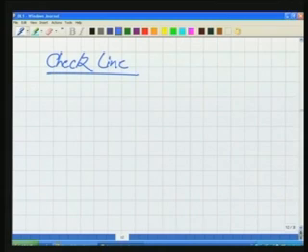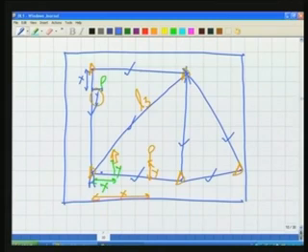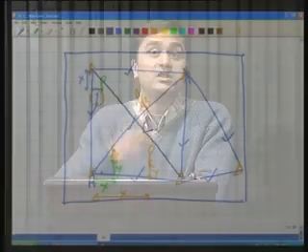Now what is this check line? Here in this diagram, had we also measured on the ground, let us say, this line. We are not using this line, which I call capital L, for plotting my triangulation figure. I am not using it for that purpose. I am using this check line later on.